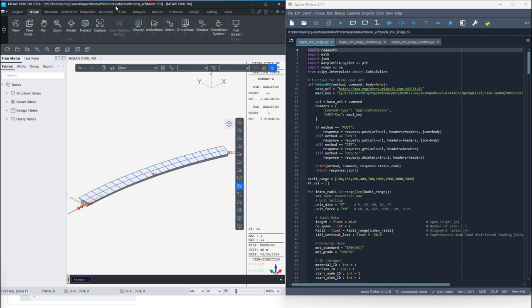The analysis has been successfully completed, and as you can see, the requested results are displayed right here. The torsional moment reactions at each supporting node are displayed. And just to mention that these are torsional reactions from dead load, which is a vertical, uniformly distributed load. If this bridge was straight, these moment reactions would be 0, but since this bridge is curved, it follows an arc alignment, these reactions are non-zero.